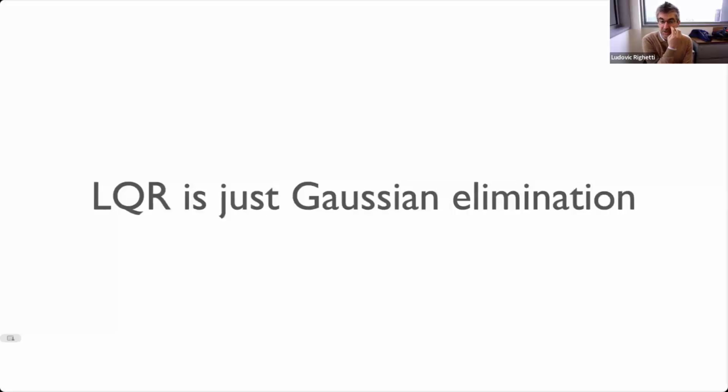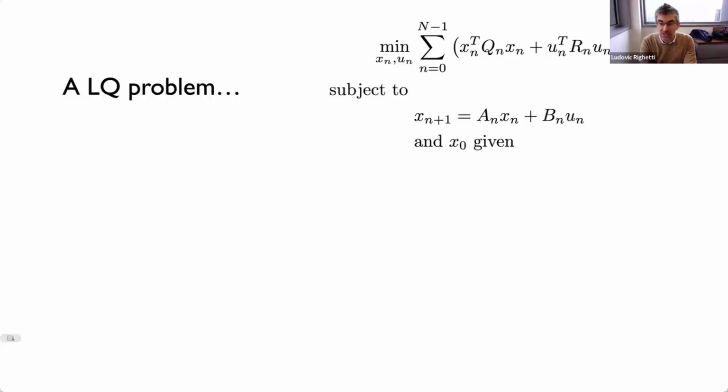And so the thing that I realized we kind of rediscovered is that doing LQR, as in iterative LQR, right, is nothing else than just doing a smart Gaussian elimination in a matrix with a certain structure. And once you understand that, we realize that there's no need to reinvent any of these DDP-like algorithms that we've been developing over these past few years. So let's start very simple.